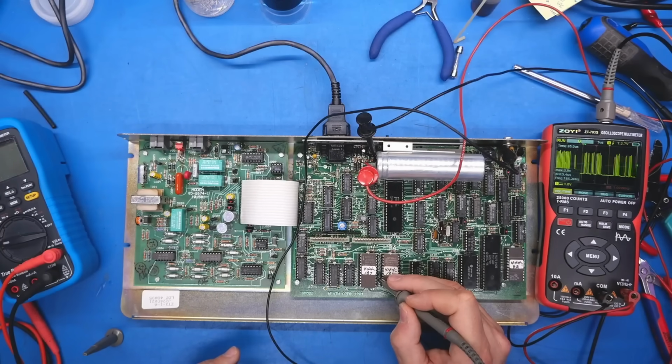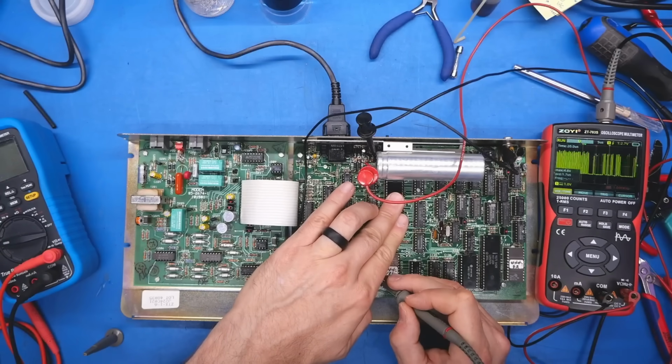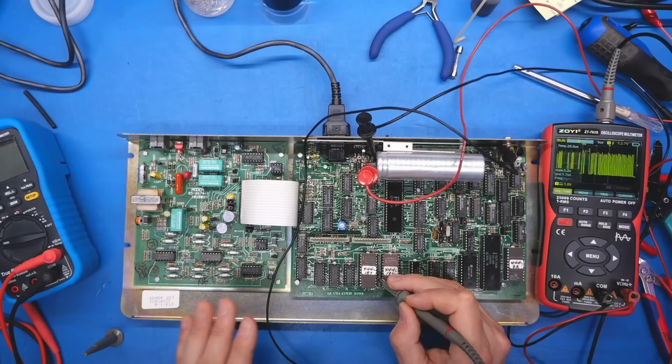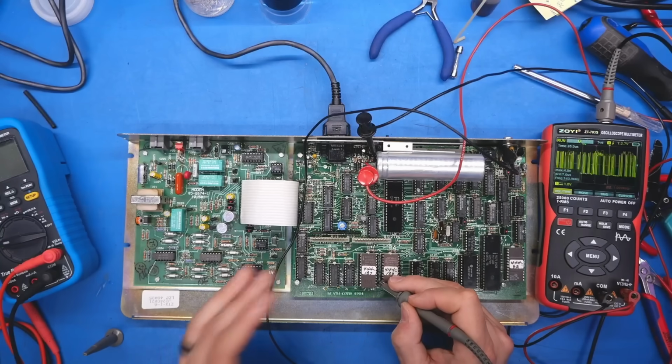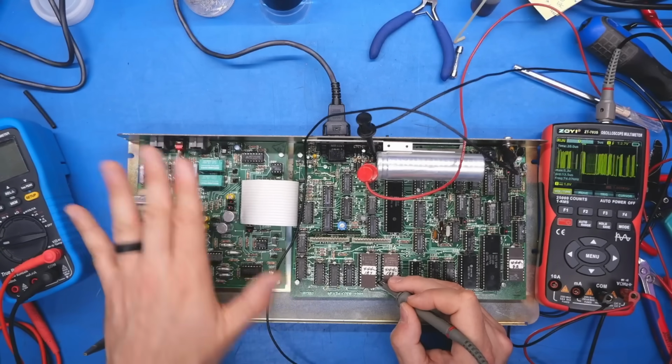Yeah, this is the data bus we're looking at. We're seeing activity. So the CPU is running code, but it's not clicking the relays, which it definitely seemed to have done. And I don't know if that was coming from the CPU before, or if that was actually just coming from the modem just powering up. So it seems that the power supply is working.